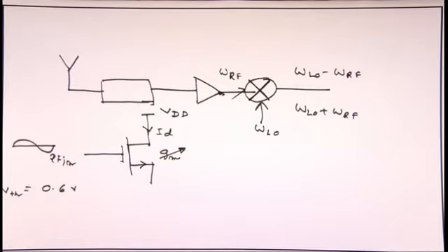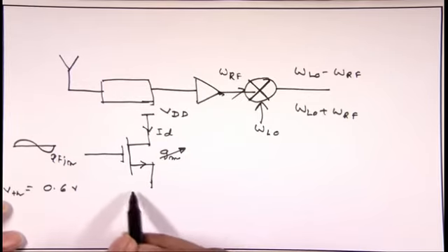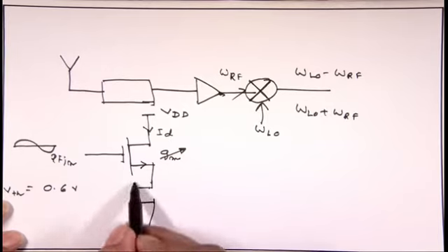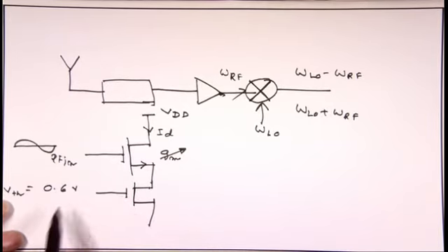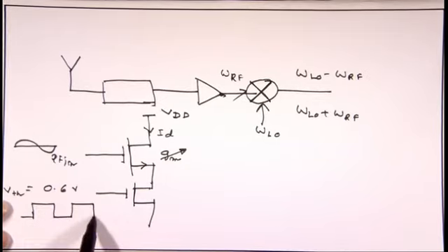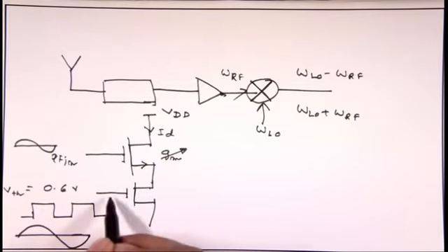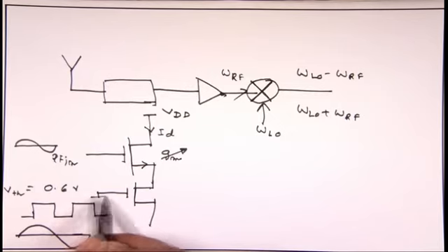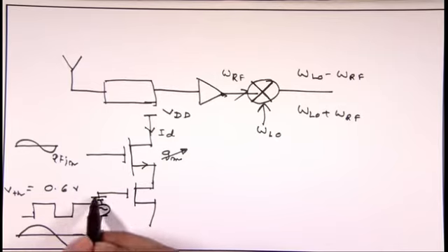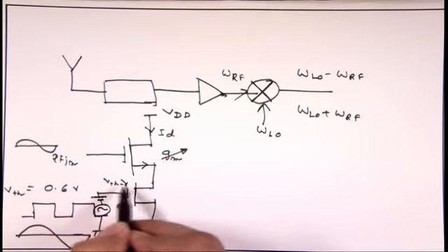but I require the multiplication. How do you multiply? Now, if you have another transistor in cascade and you apply some square wave or sinusoidal, depending, I will take both of the cases. What will happen? You are again giving some sort of a bias along with the AC, and the bias is, say, 0.3 volt, and the VTH of the transistor is the same, 0.6 volt.